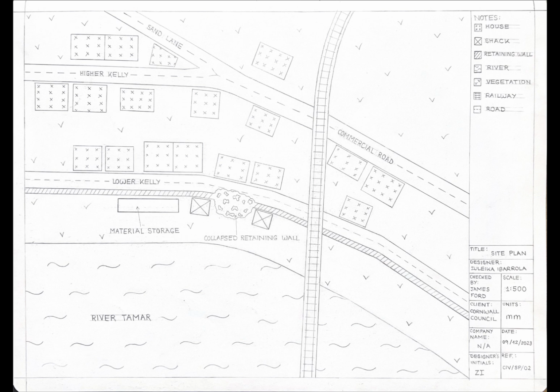Retaining walls are built on sloping terrains to prevent soil erosion and to resist the lateral pressure of soil, stopping the soil and debris spilling onto property and causing damage. In this case, it is built between the area of the River Tamar and the residential area due to the difference in the heights of the soils.